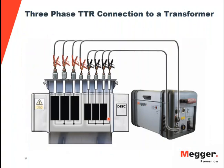Especially for excitation current, you will see an influence of the remnant magnetization of the core on the results. So you would prefer to do the winding resistance at the end, and before energizing the transformer, demagnetize it. And if you did winding resistance first, you would like to demagnetize before you do any AC testing.